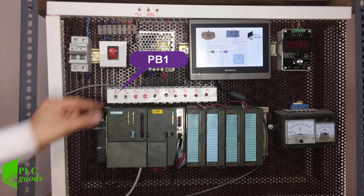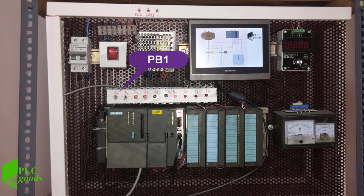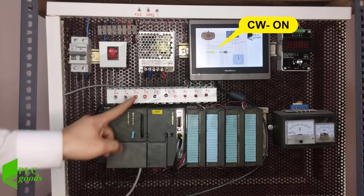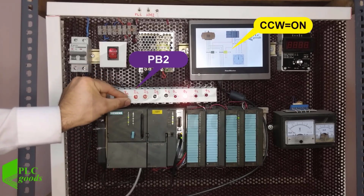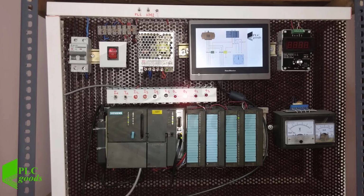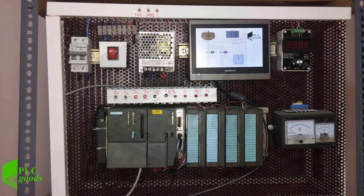I depress PB1, the CW contactor turns on, its color goes from green to yellow. I depress PB3 to stop the motor. I press PB2 to turn on the counterclockwise contactor. I press PB3 to turn it off.